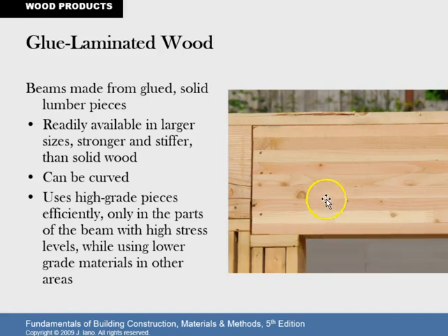And then when we move to the middle of the beam, the compression and the tension becomes nil, zero. It meets at the neutral axis, and there is none. So this is all to say that the upper face is experiencing the highest compression stresses, and the lower face is experiencing the highest tensile stresses.